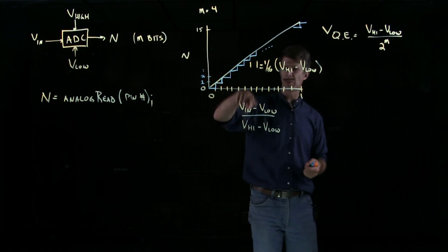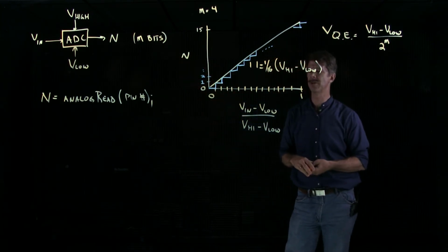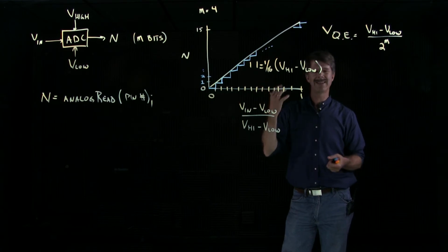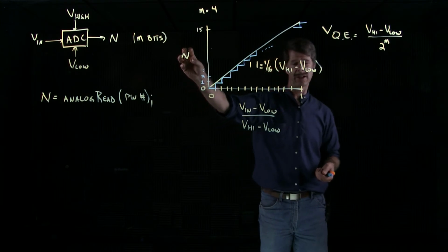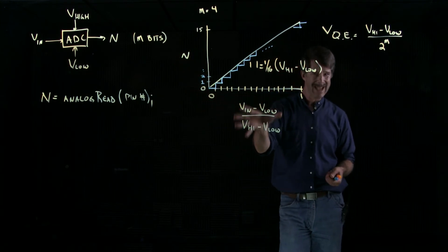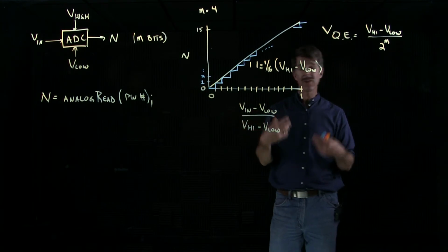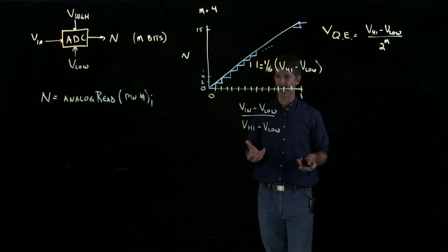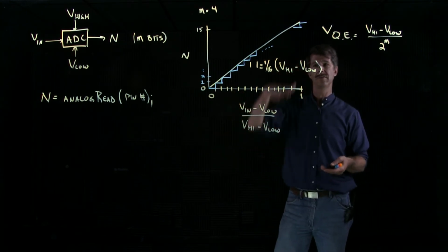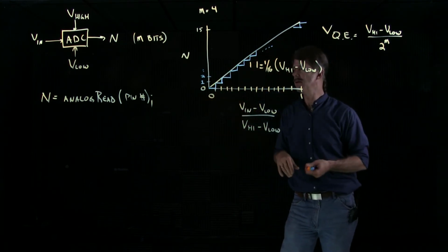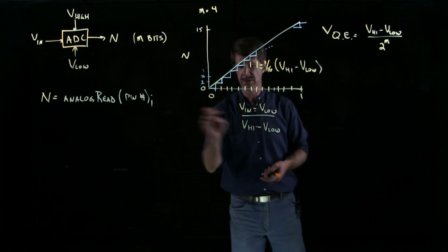So that is a simple process of inverting this equation, which is the reason I've written it all down for you. That tells you how to take this integer that you get inside the computer, do some math in your sketch, and come out with Vin. Very likely, this sensor you're using, maybe a temperature sensor, has its own equation, ideally a line if life is good to you, which relates the temperature to the voltage that was on this pin.